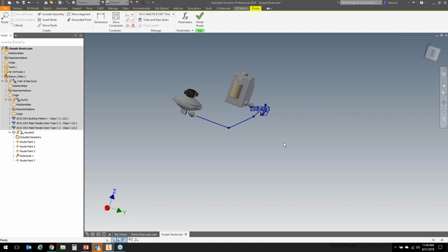When you do rigid pipe, it does essentially require that you put those in first, they don't have a start fitting or an end fitting. So if you decide, yeah, I want to switch to flexible tube, you could replace those original fittings and then possibly either delete your route and start over, or change that style. You can switch that over.